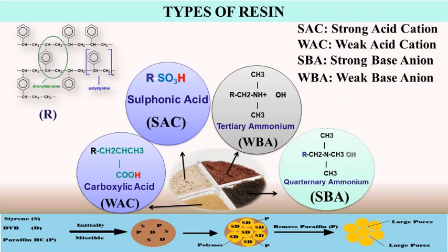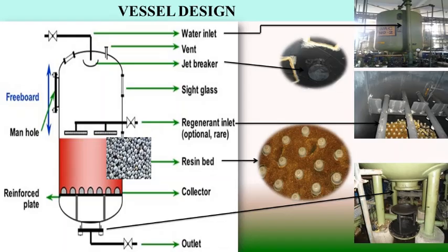So activated carbon filters are actually removing the residual turbidity below 2 NTU, and they are also removing the color and odor of the organic substances present with the raw water, and residual chlorine presence may be reduced to nil level. Up to 0.5 ppm it can arrest.